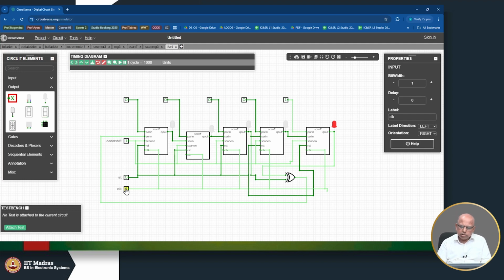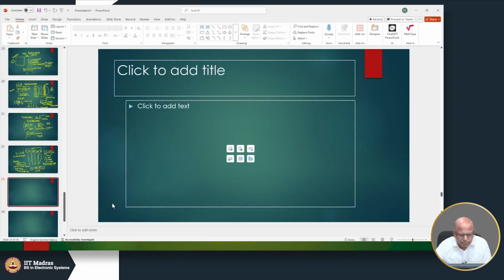So, this is an example of a linear feedback shift register. In this example, we took 1 plus x cube plus x power 5. There may be other characteristic polynomials which will also work. So I want you to try this exercise. Build an LFSR